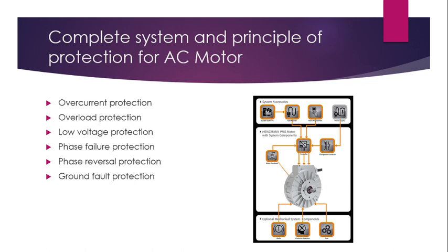For phase failure protection, it is used to protect the motor in case of any phase failure during the operation of the motor. The phase reversal protection is a protection technique that is used to protect a motor from the phase reversal condition. Lastly, ground fault protection is used to protect the motor from different short circuit conditions.